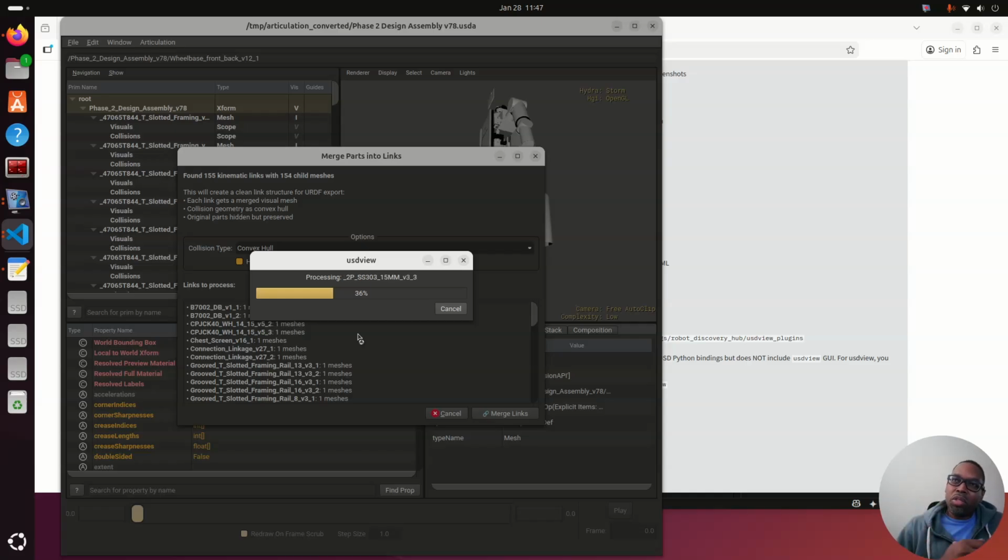So we're going to the most simple URDF possible while retaining the shape. And that's another thing when we go to test these things, because usually you create a URDF file and you simplify it so much that sometimes you actually simplify it down past points which are important to the simulator.